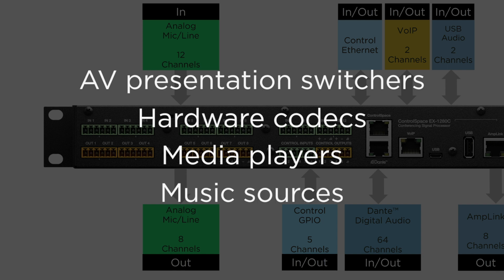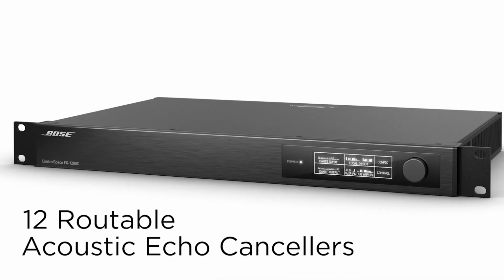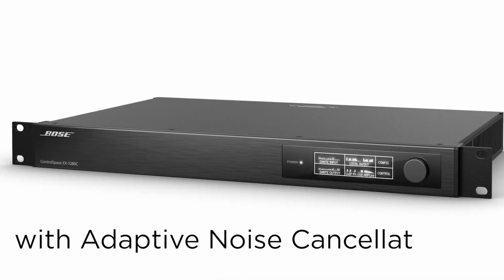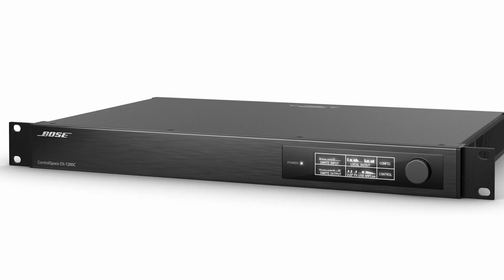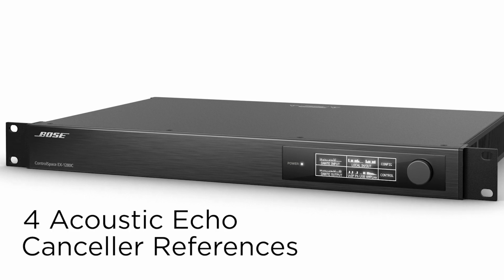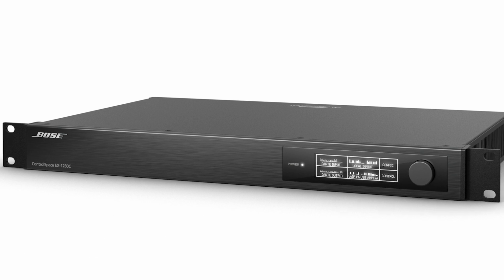The EX1280C incorporates 12 routable acoustic echo cancelers with adaptive noise cancellation, nonlinear processing, and comfort noise to enhance the meeting clarity and intelligibility. 4 AEC references support multiple rooms and zones.